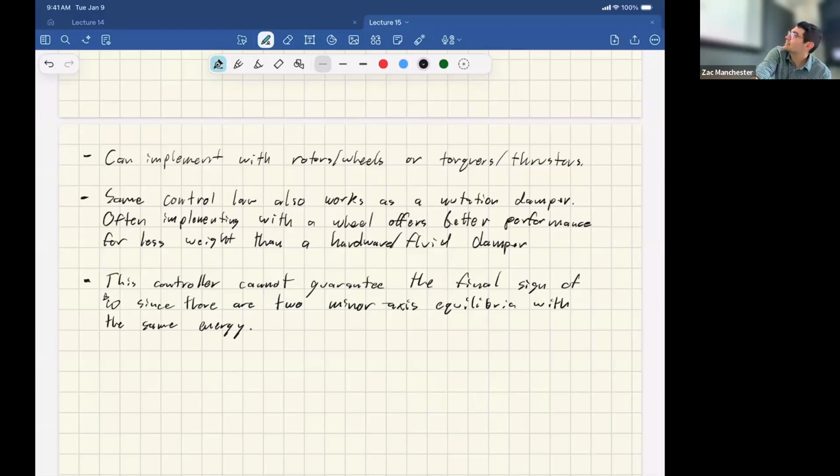Here's what you end up with in the end. And we used a switchy flavored thing instead of a linear thing. We had this conversation last time, right? We use a tanh for a couple of reasons, it has some niceness properties. You get two tuning parameters. You can set the saturation, and you can set the slope with this alpha, which is convenient. And then here's what it looks like.